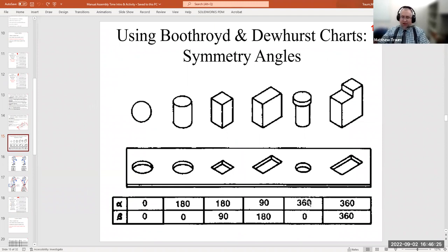So long as you get it aligned to go in the hole, you're good, and beta is 0, and you have to account for the time that it takes to rotate it in the insertion step, not in the handling step. So that's why this is the way it is. Okay, so any questions about these shapes, with the exception of this one, which I'm going to talk about in a second, and why their numbers are what they are? Okay, I think everybody's good.